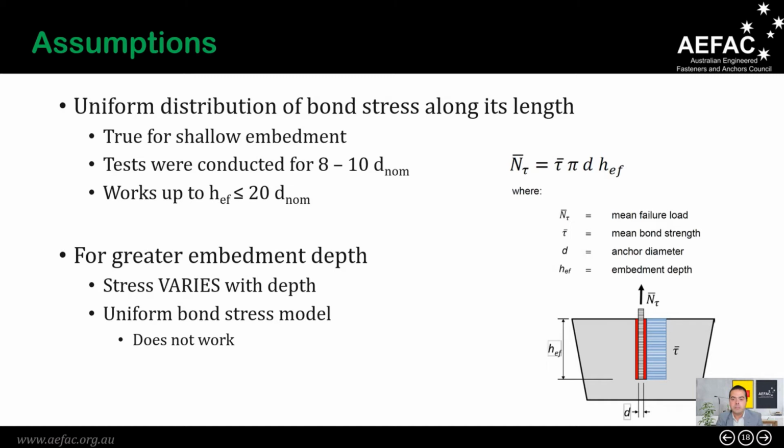For the deep embedded anchors, the stress varies with depth, or it decreases as you go deeper. So we cannot use the anchor model from AS 5216 to calculate the pull-out capacity for deep embedded anchors or the deep post-installed reinforcing bars.